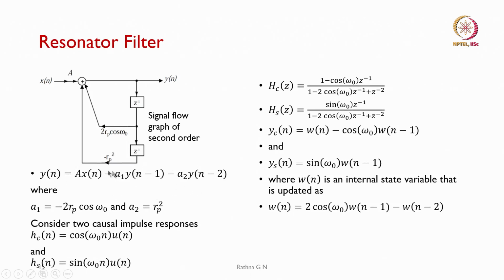So, with this IIR filter with 2 feedback terms, we can calculate the amplitude with 2 initial values, because it is an LTI system. Usually we give initial conditions of 0, and then by giving x of n equal to 1, it automatically starts resonating. Then we can generate different sine frequencies and use it in our sine generation.